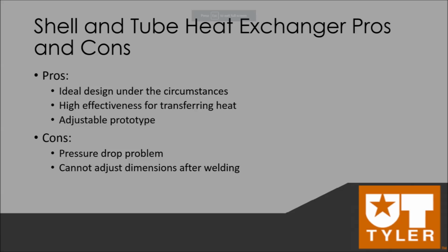This type of heat exchanger also has a very adjustable design, as we can change the number of tubes, tube passes, tube diameters, and so on, as well as the shell area and, of course, the material. Pressure drop could be a possible issue as we have many turns, bends, and corners, unless we attempt to make a circular shell design, which is a lot harder to machine. We will also have to insulate the entire box in order to keep our effectiveness high.